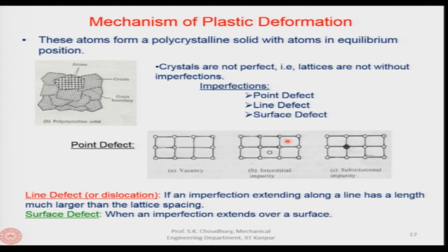Similar thing happens in the lattice structure of the material. These are the defects which the material does not want to be there. For example, in case of vacancy, the material will always try to have one atom here. So this atom will come here, next will be vacancy here. So this atom will come here, and so on. This will be moved because this is something which the lattice structure does not want, it is a defect.